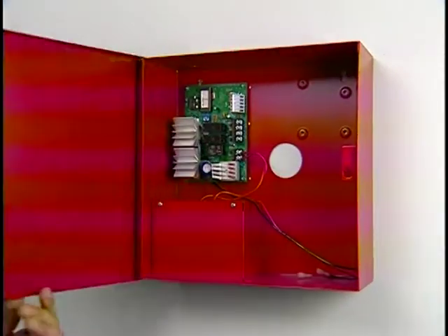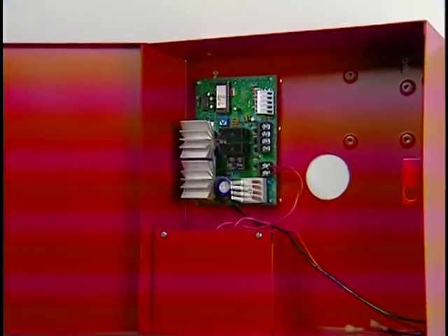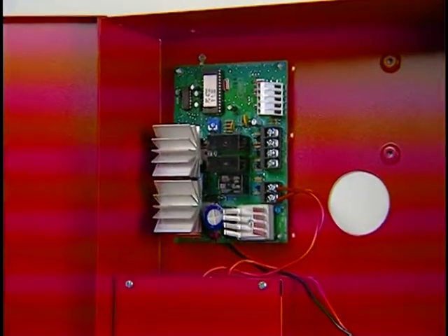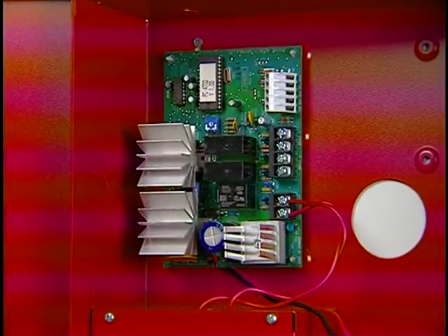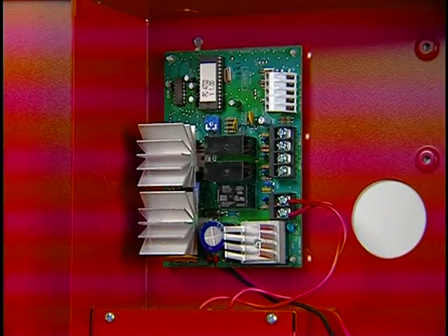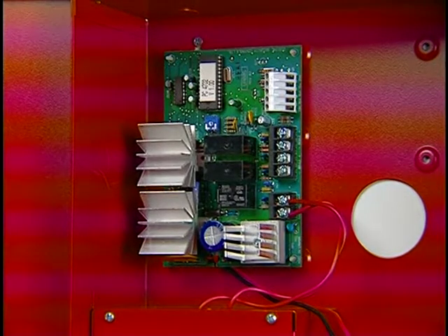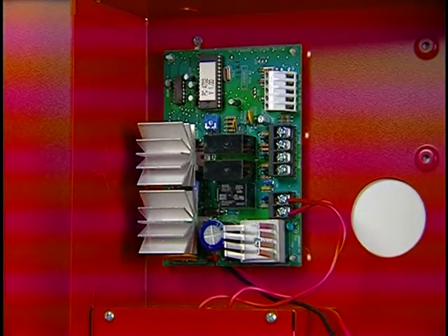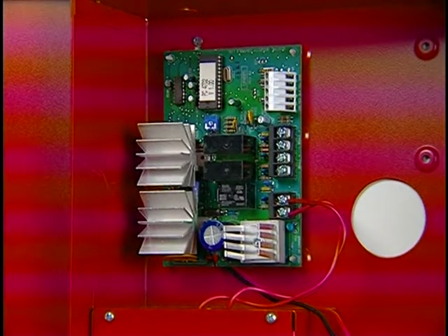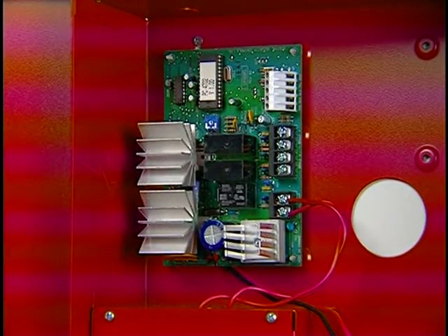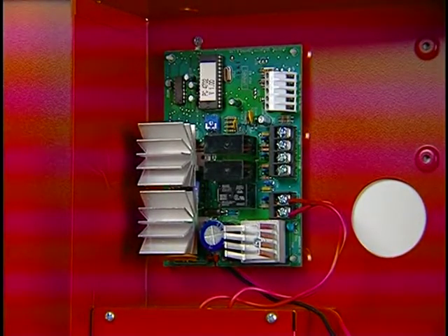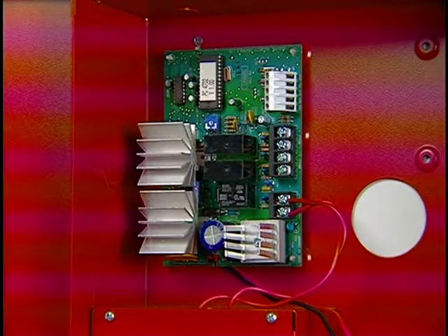The PC4702BP, or Bell panel, is a module that will provide 2 fully programmable, fully supervised 24-volt DC outputs, each rated at 1.8 amps. These outputs are typically used to activate horn strobes or other 24-volt notification appliances. Up to 4 modules can be enrolled to the system for a total of 8 outputs.